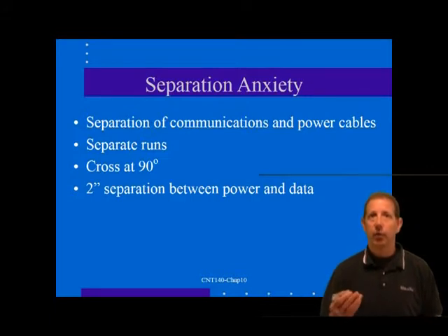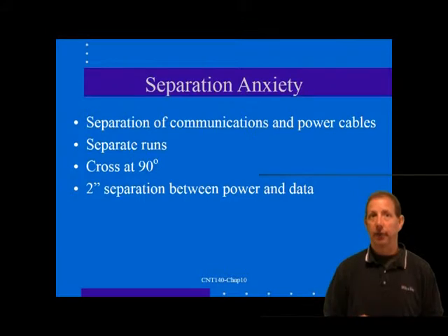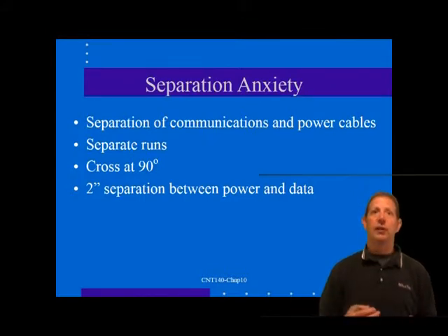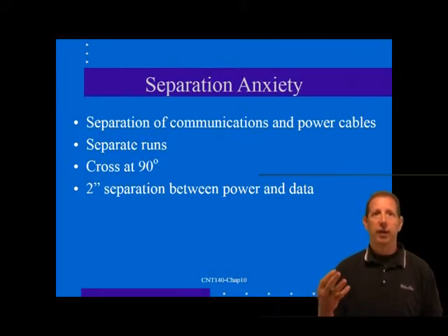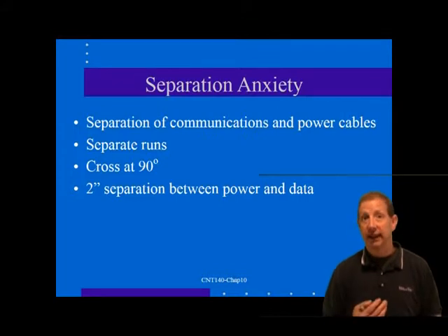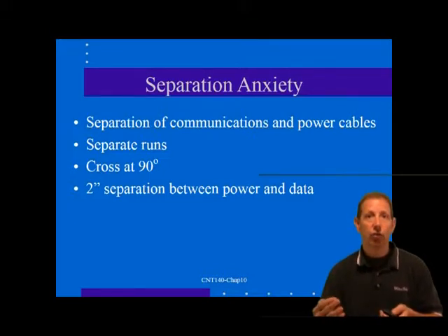In other sections of the book, we've discussed the issue of separation from power cables. Many authorities have attempted to create guidelines on this issue. The recommendations range from a 2-inch separation in electrical codes all the way to a 3-foot guideline from building standards. This leaves a lot to the imagination. So what issues should be considered?